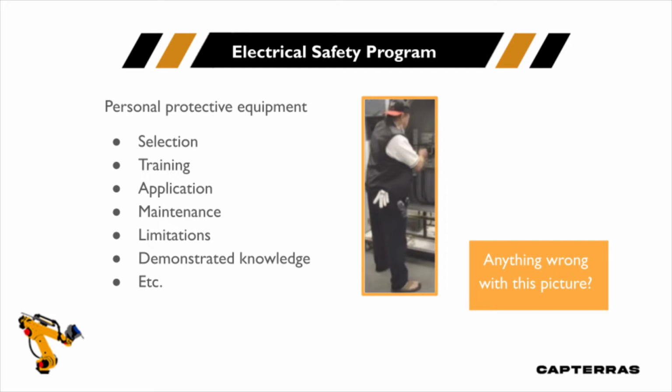So demonstrations of knowledge and limitations of PPE are all things that should be covered. In other words, do we have folks demonstrating their knowledge of PPE? We can provide training to them. We can make sure that we hand them a bag of PPE, but can they demonstrate? Can they go up and read a label, explain what that label means, the incident energy, and explain what working distance means, and actually be able to say, here's how I go about picking my PPE, the thought process I use to select my PPE.